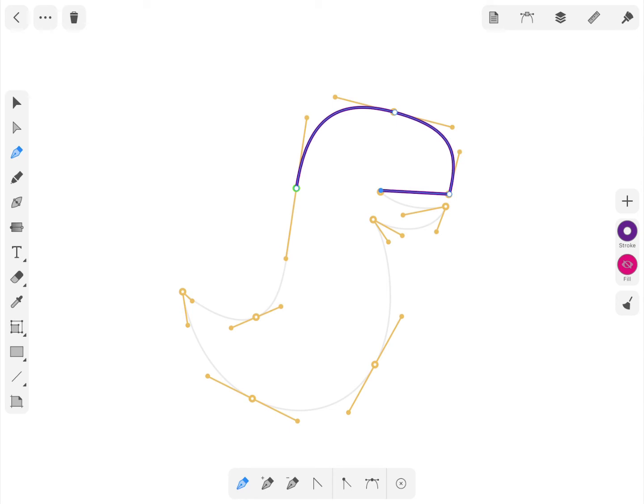Tap once without pulling out the direction lines. Move on to another point, tap and drag to create the curvature of the lower jaw. As always, make sure the length and direction of each handle corresponds to the auxiliary lines. To continue drawing, we need to learn how to split the direction lines and give a path an alternative direction.